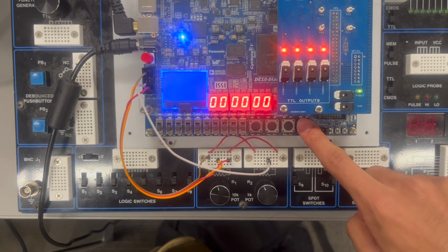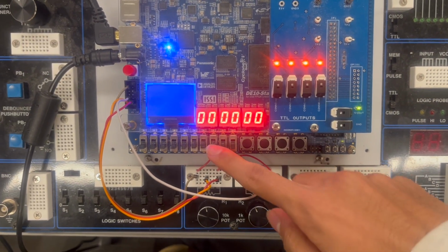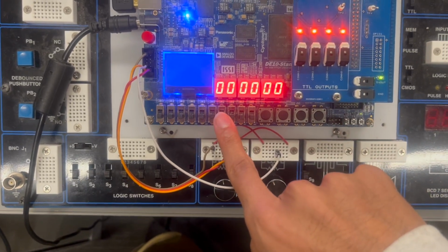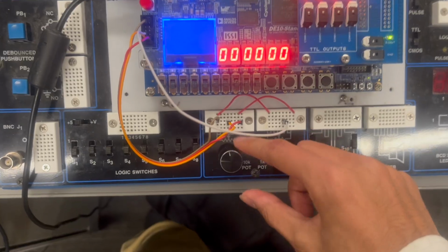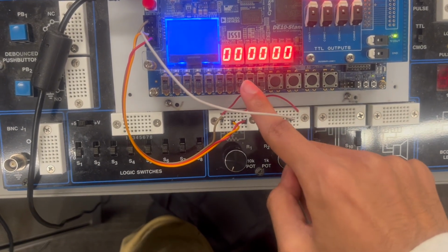Now we restart. If we don't want to use preset goals, we can set them here. We make it so when we set them, it shows the status register on the LEDs. We set the dial to all the way left and then lift the switch. The right LED is the fresh data bit and the left is the in progress bit.